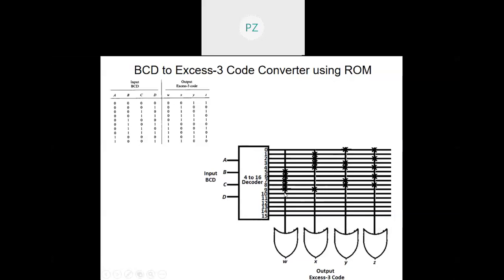One thing I would like you to notice, that since BCD inputs 10, 11, 12, 13, 14, 15 are don't care, none of these min terms are connected to any of the OR gates, right? So this gives me a clue, which we are going to take as the next topic: just as we have kept this OR array programmable, why don't we keep this AND array programmable also? That will give rise to yet another device, which is called the Programmable Logic Array, PLA.